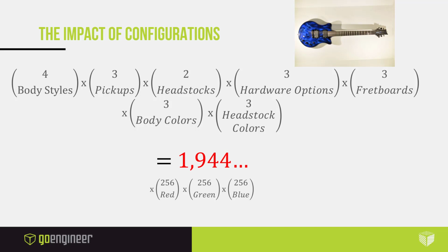There's some settings that you can do to have that offload the information. But ultimately, if you offload the file size, you're waiting for it to load every time you change configurations. So you're going to eat that data load into RAM no matter what you do. If you take a 50 meg assembly, right, times almost 2,000 configurations, this model is gigantic, right?